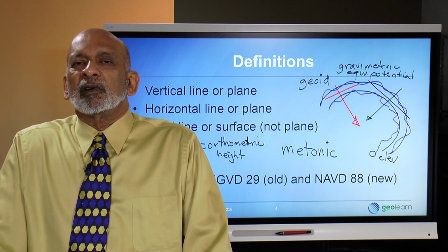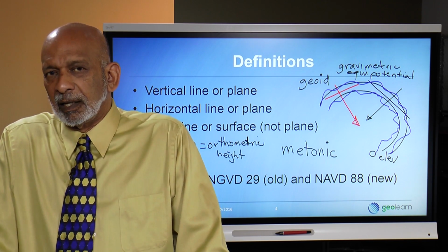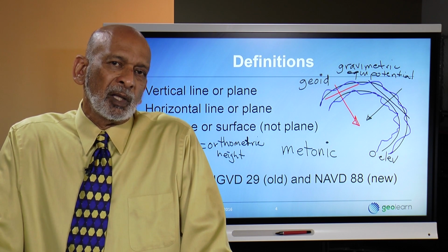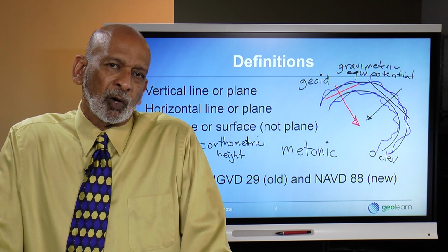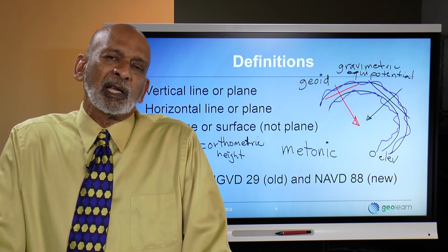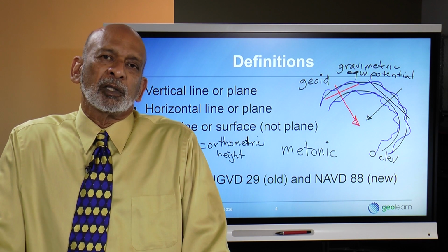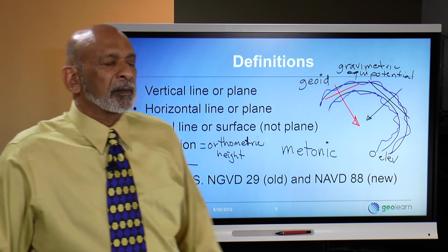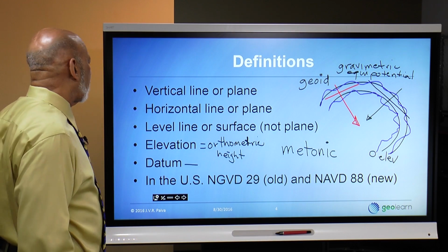And then I'm going to very carefully differentially level to all the parts of town where we need to know the exact slope of the sewer or how deep the sewer needs to be under the surface of the earth, so that we can use gravity to bring all the sewage to that one common place, which is the sewage treatment plant. So this is a very common thing that's done.